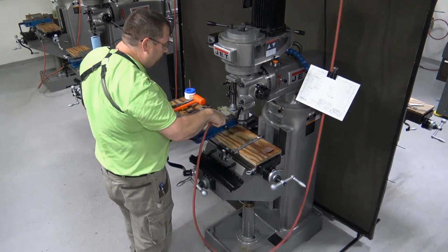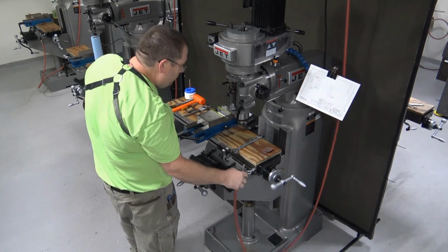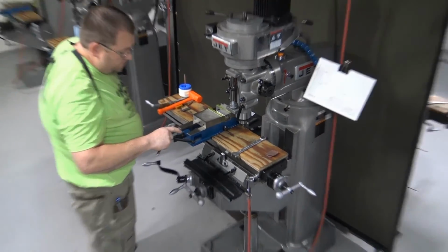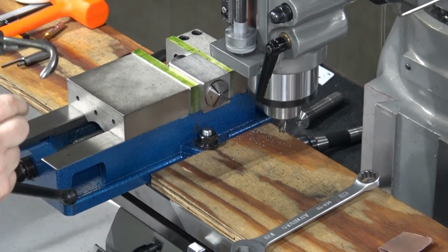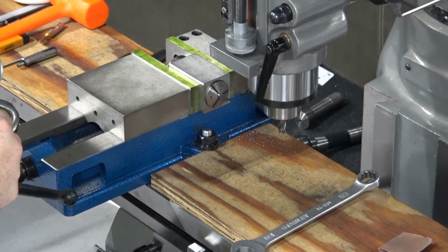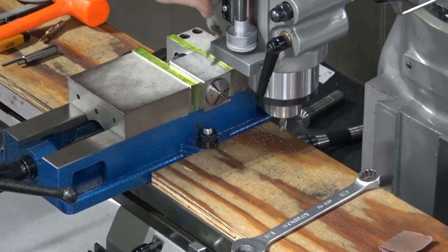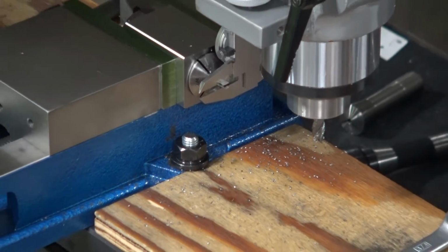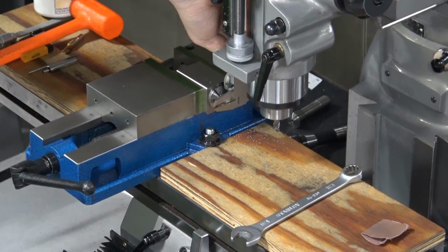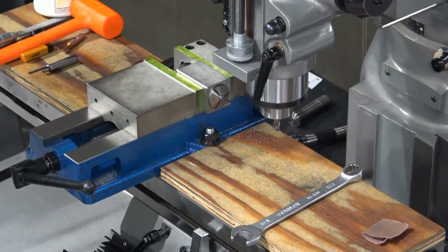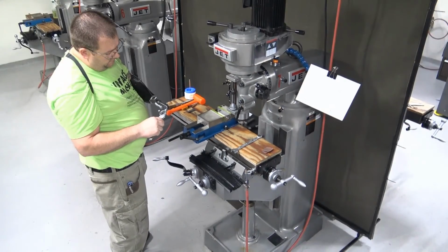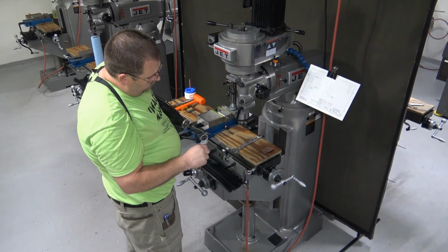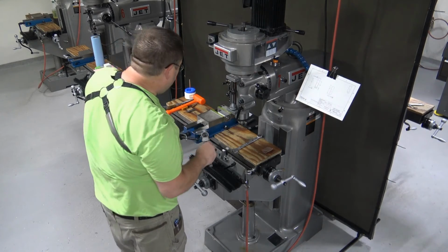Now that 75 has a tolerance on it. I'm going to blow the chips off. I'm going to take my calipers and I'm going to measure that thickness, right? I want my thickness to measure between 170 thousandths and 175. That takes into account tolerance, okay? We're going to measure that thickness. I'm going to rock it back and forth so I get a good accurate measurement. And I'm at 187 thousandths. So 187, I have to be 12 thousandths down to get to 175. And I believe we said that we were going to target 172 and a half. So 12 plus 2 and a half is 14 and a half.